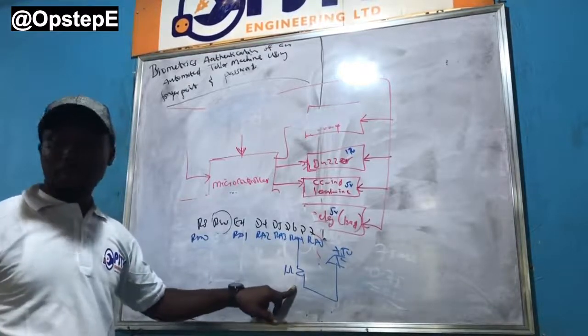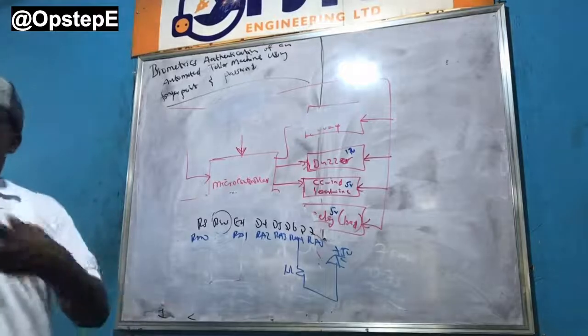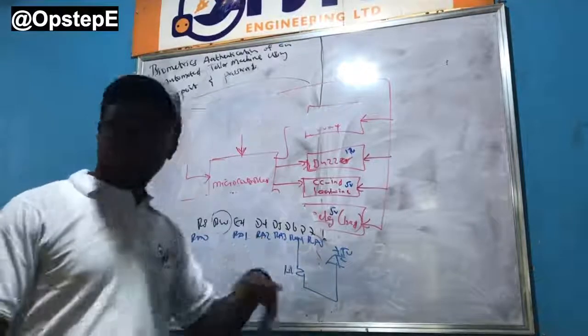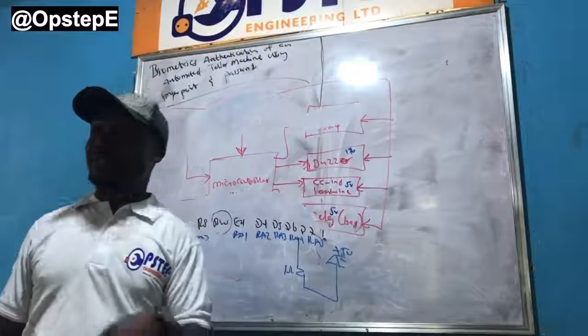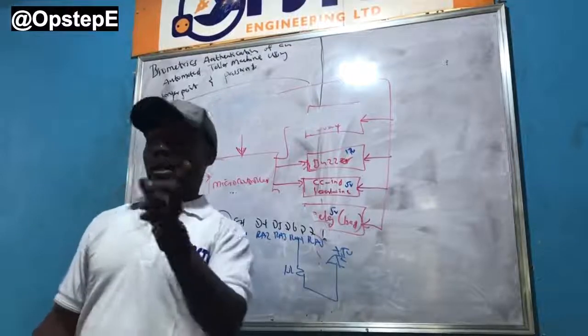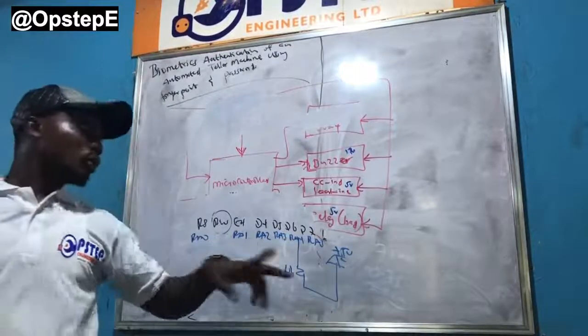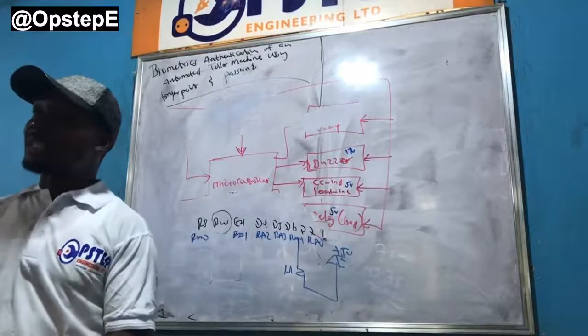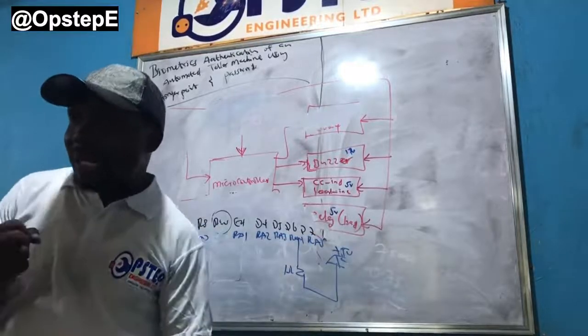It's important. And don't forget that from the anode of your LCD, which should be pin 15 of the LCD, another resistor is taken to VDD. That way you are limiting the amount of current that the backlight is using.